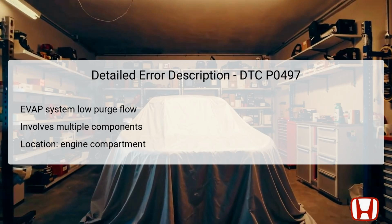A decrease in the purge flow indicates that the vapor cannot move effectively through the system, which can lead to performance issues. The FTP sensor monitors the pressure inside the fuel tank and sends relevant data to the Engine Control Module, ECM. Understanding where all these elements are located and how they interact is essential for troubleshooting.